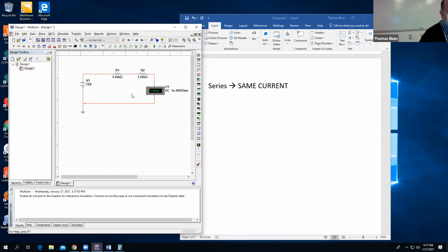Okay. Now you see that 7 didn't change, but that's because I have not rerun the simulation. This is not right. The system doesn't clear out, doesn't say, oh, you made a new circuit, let me clear out the ammeter reading. It doesn't do that. So it can show you, this is not the right answer. Let's rerun the simulation. Okay, so now we have less current.